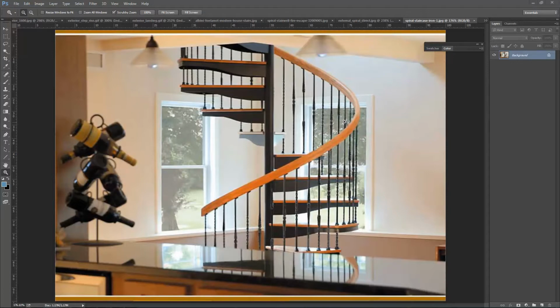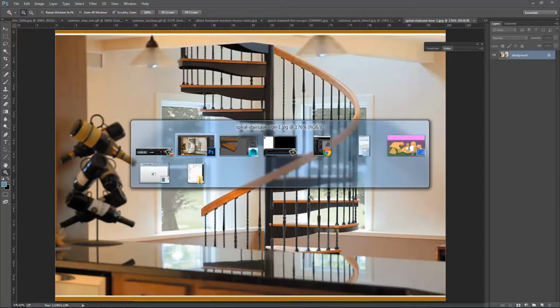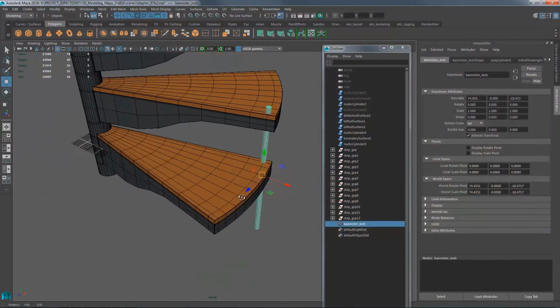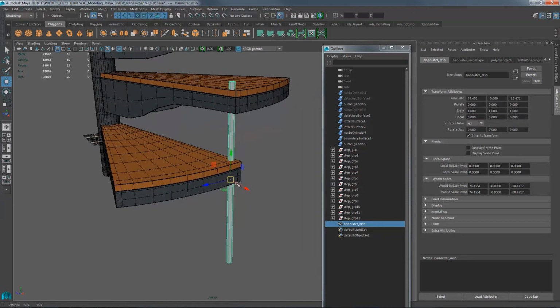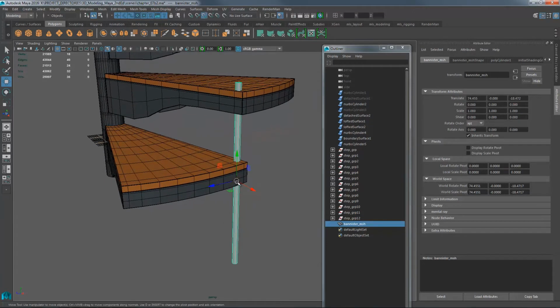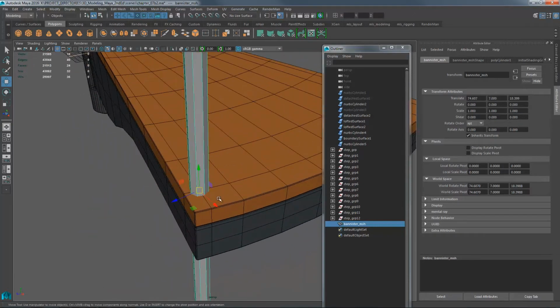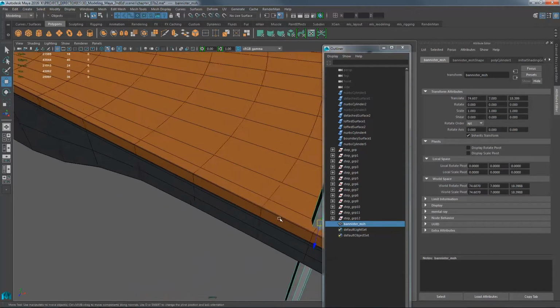Then we're going to produce the remaining banisters to match that handrail, because I want to be able to get a nice, clean curve all the way up, and the only way I know I can get that clean curve is by having one point to snap to per banister. So here's how it's going to work. I'm going to come over here, and we're going to put the banister, snap it to, say, this vertex right here on the edge, just hugging the edge right there, just like the reference shows us.